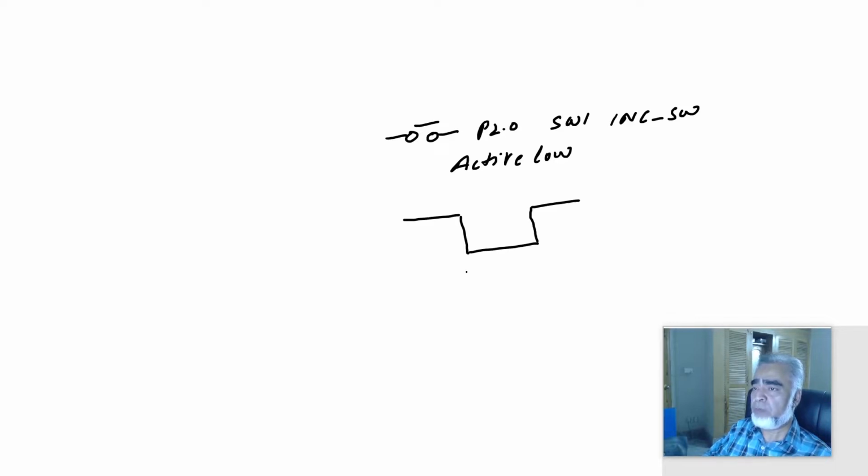When we press the switch, we'll observe bouncing on the falling edge and the switch will go low, and when we release the switch, again we will observe bouncing and then it will go high. So we'll use a technique to filter out these high frequencies. We'll use a digital filter to filter out this frequency.